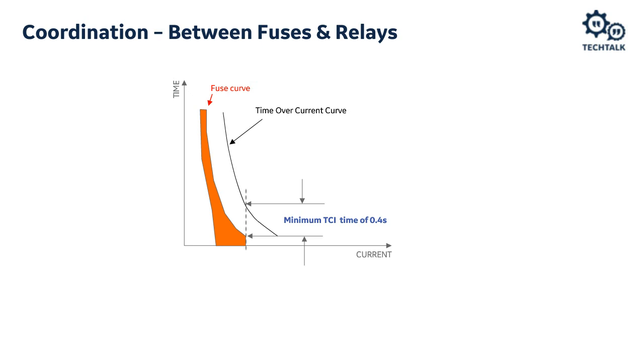Likewise, if we have an electromechanical relay, which can drift and have shift in it and needs calibration, we typically would want a longer time coordinating interval than if we had a microprocessor.